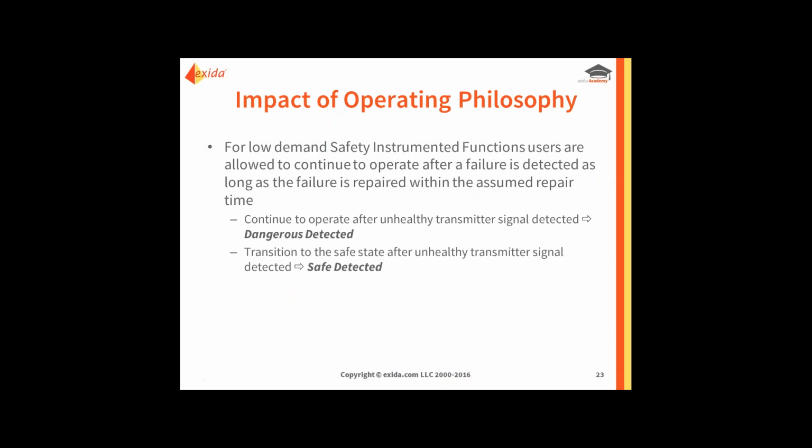Then we have different operating philosophies, and I kind of hinted at that already a little bit. In low-demand applications, the standard allows that you continue to operate after a failure is detected, as long as that failure is repaired within the assumed repair time. So if you assume a repair time of 8 hours, you need to fix your problem within those 8 hours, or you need to transition to the safe state. Some companies like to do that.